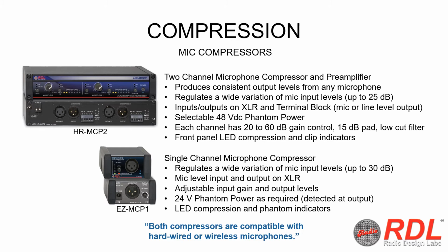Both of these mic compressors are compatible with hardwired or wireless microphones. For wireless mic applications, simply connect the wireless receiver's mic level output to the compressor so you bypass that receiver's internal mic preamp, which is vulnerable to clipping.